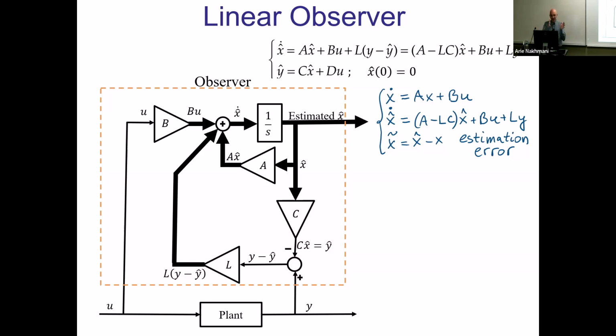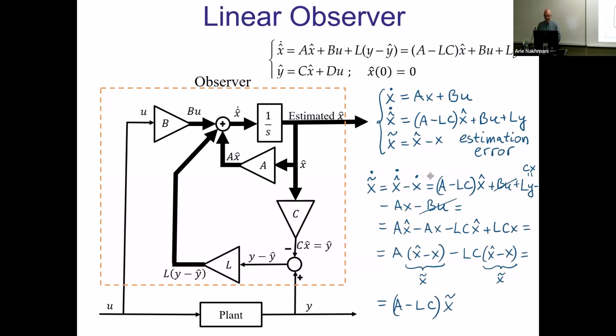So you want almost in zero time to converge to whatever you want, right? Okay, so let's see what happens to that X tilde dot. We will write the equation for X tilde dot, how it is converging, how fast it is converging. If you remember, when you get to the equation X dot equals AX, the convergence depends on the eigenvalues of that matrix A, right?